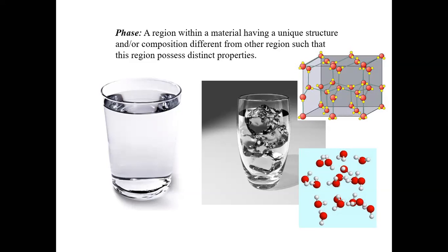In this case, no, it wouldn't have a different microstructure, because if everything crystallizes into this crystalline form of solids, it will eventually have the same crystalline microstructure, but it may have a different orientation of the axes, okay? So we're going to have a polycrystalline ice. But now let's talk about homogeneous nucleation. Let's say the system is very large. We do not care about what happens on the boundary. We just care about what happens in the bulk liquid, right?